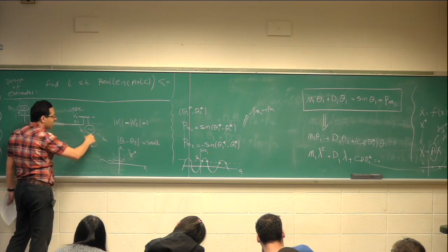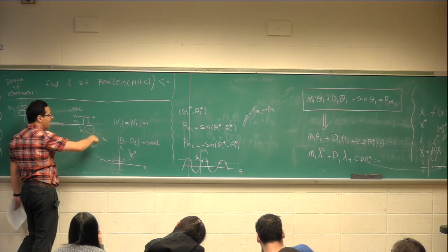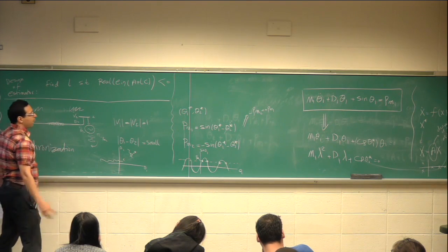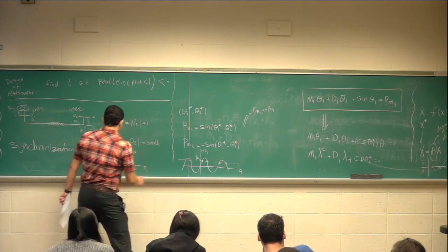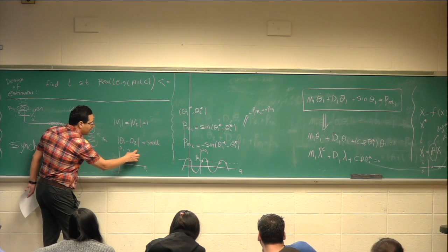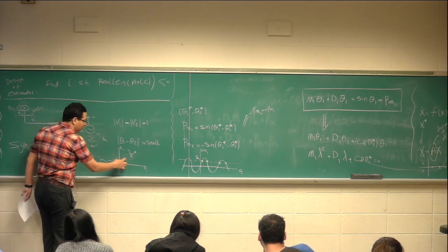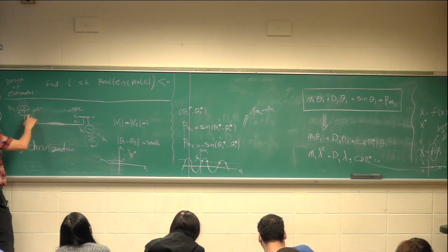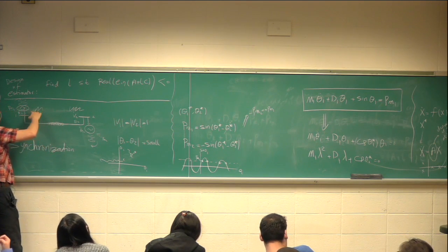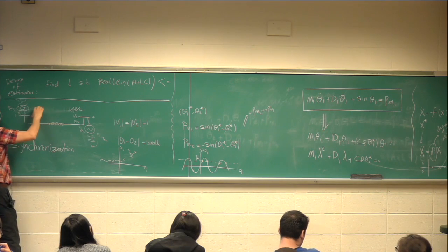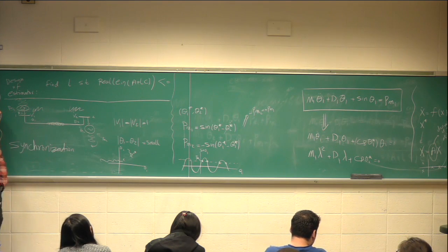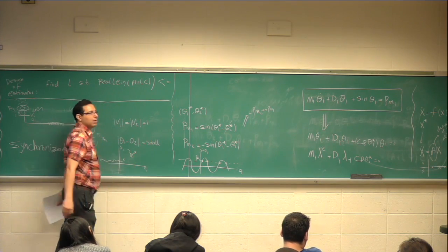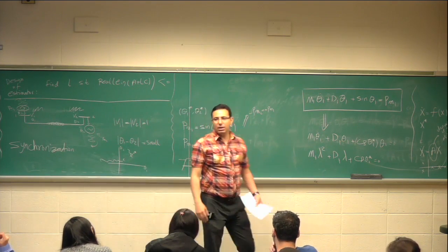And I want to make sure that if there is a little disturbance here, that's a transient, that disturbance is a little disturbance. It doesn't make it very fast or make it very slow and eventually stop. That's the stability. And for stability, we have to make sure that if I perturb the equilibrium a little bit, I come back towards it. If I perturb it a little bit, it doesn't go towards infinity. This happens if I calculate the voltages. They have magnitude and phases. The phases of these two signals are not too far away from each other. So this concept comes out of stability. And this is called synchronization.